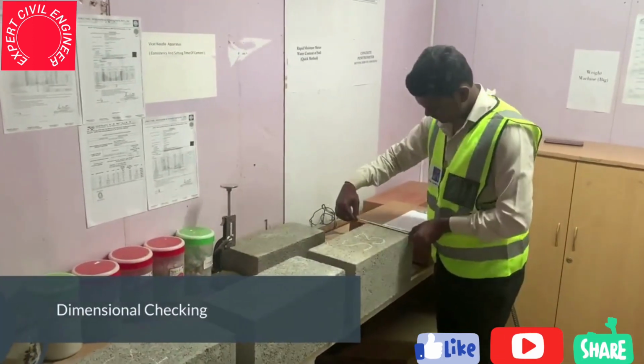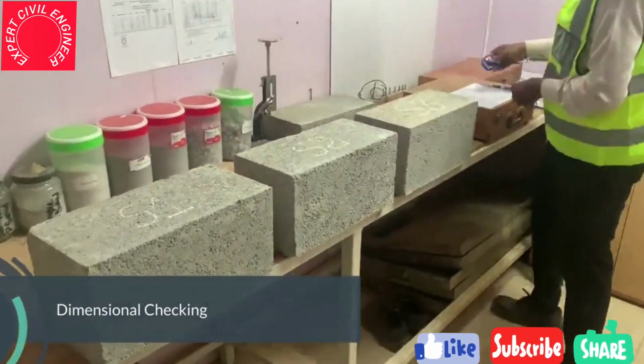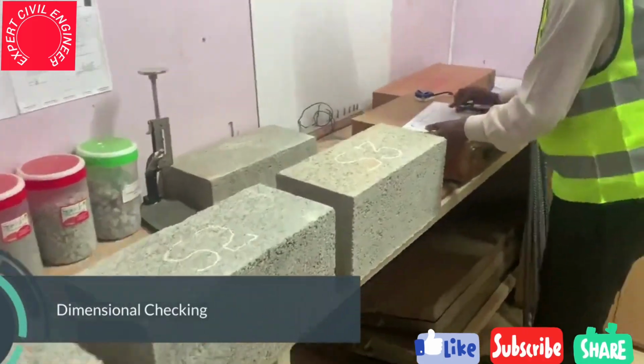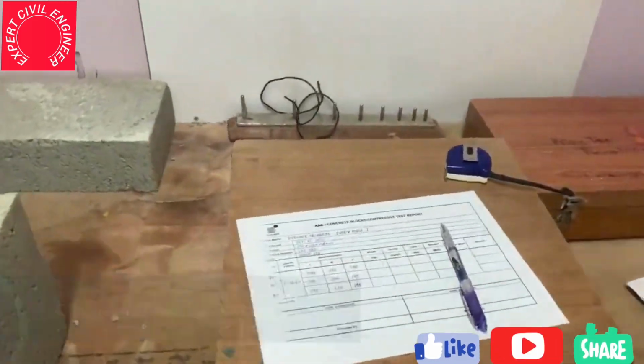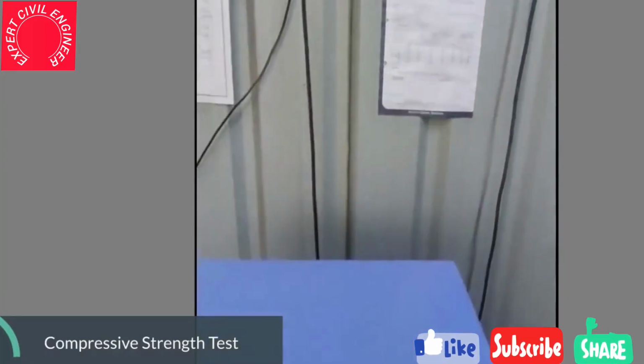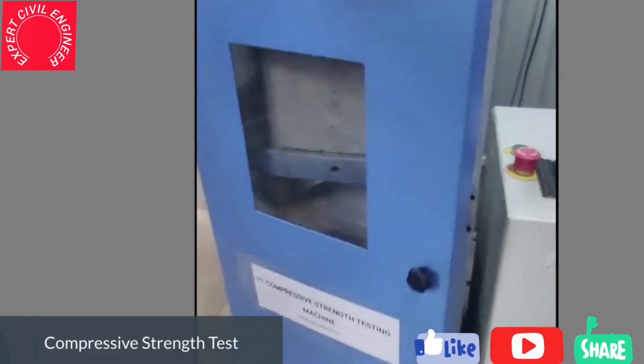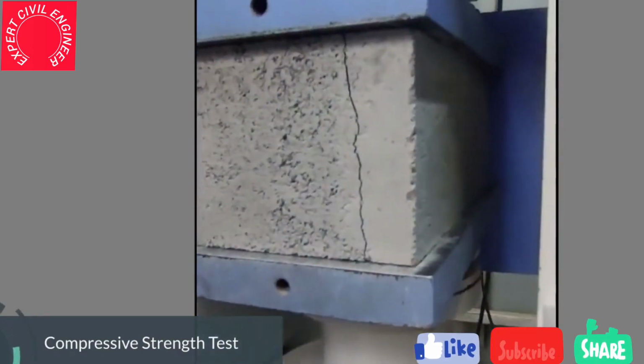The block needs to be tested for dimension, compressive strength, density, water absorption, drying shrinkage and moisture movement in the in-house or external laboratory. In the event of considerable deviations in the test parameters, the block lots to be marked as rejected and not to be used for masonry construction.